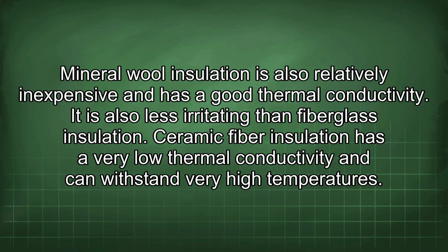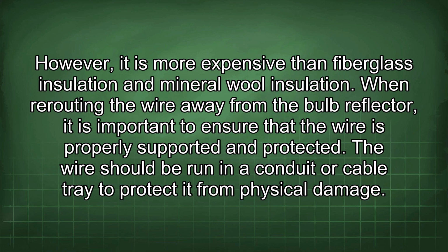Mineral wool insulation is also relatively inexpensive and has a good thermal conductivity. It is also less irritating than fiberglass insulation. Ceramic fiber insulation has a very low thermal conductivity and can withstand very high temperatures. However, it is more expensive than fiberglass insulation and mineral wool insulation.